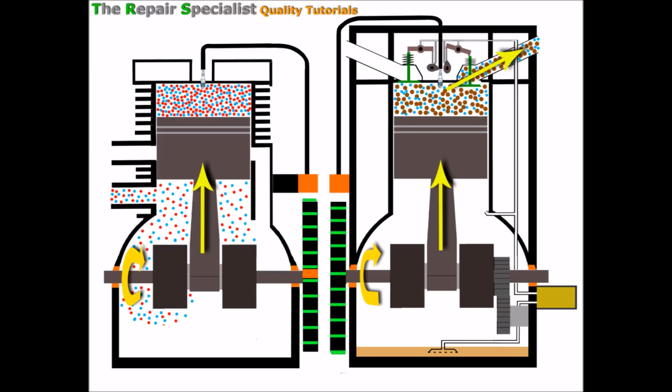And because at this point the rising stroke of the piston is pushing those exhaust fumes out, we call this the exhaust stroke. And if we have a look below the piston here, we can see how different it is to the two-stroke. There's no compression down here, so there's no air and fuel coming down here to be compressed and transferred up to the top of the piston. And indeed, this piston is acting as a piston only, rather than a piston and a pump, like the two-stroke.